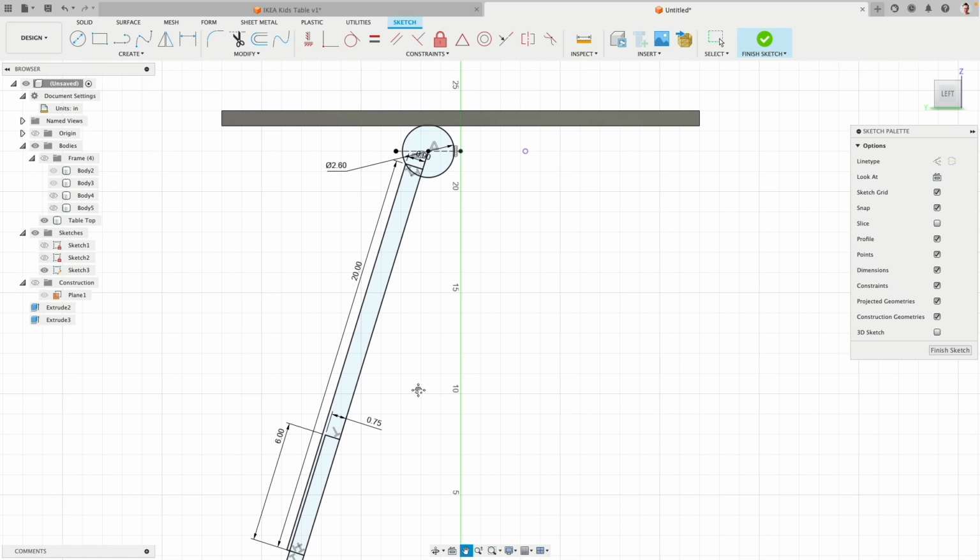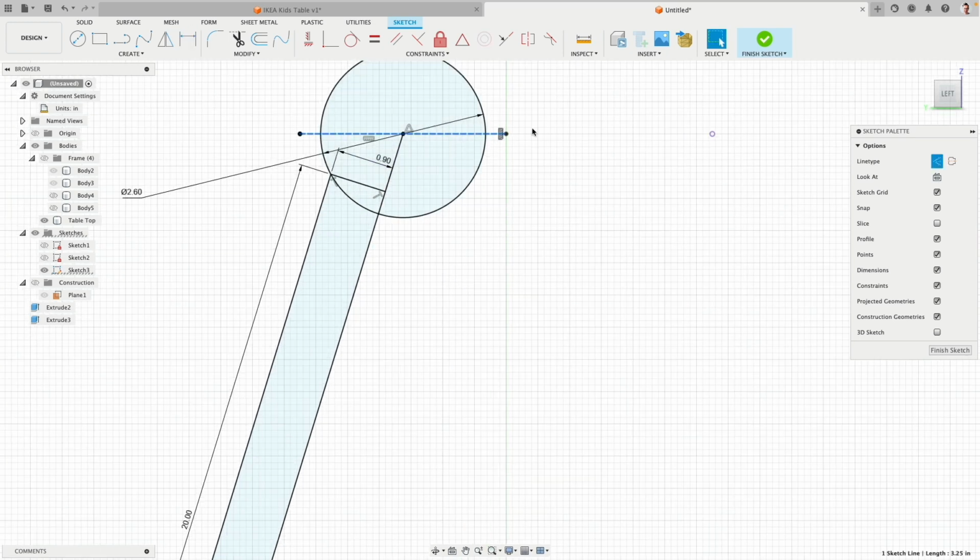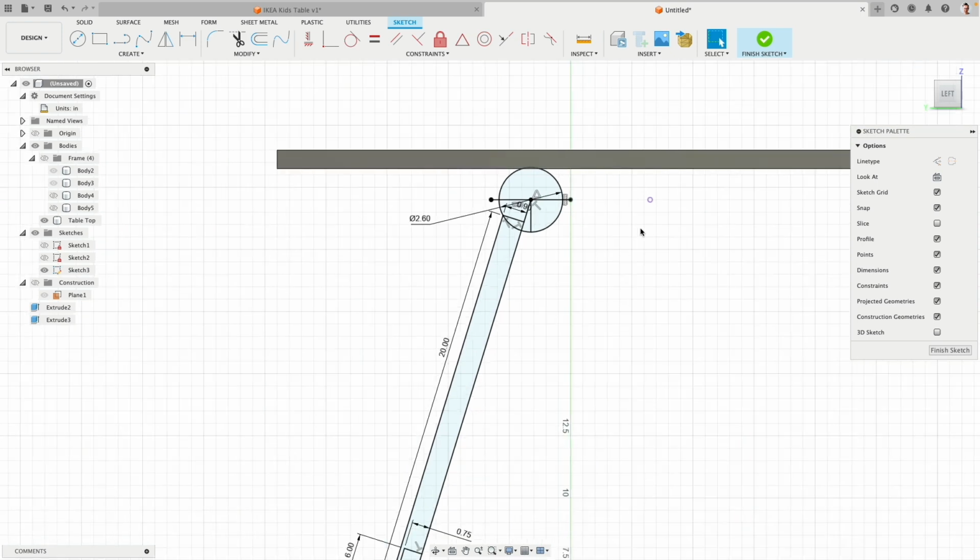Now this actually doesn't look too bad. Let's do a quick prototype. I press escape and I have here set this line to a construction line. I realized that's actually not smart. So I turn this off and I will add a line down here. This line should go straight down. You see, this is actually now this quarter part of the circle I need for the revolve command.